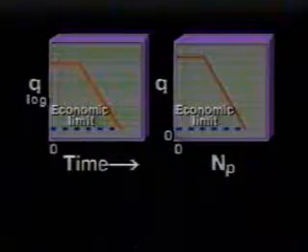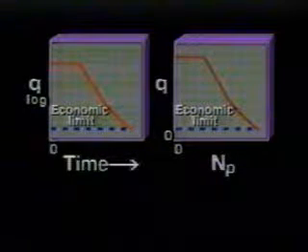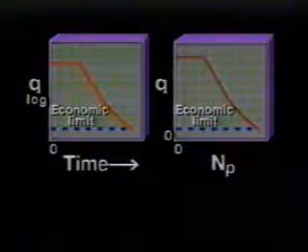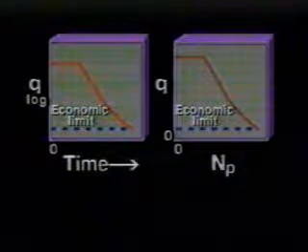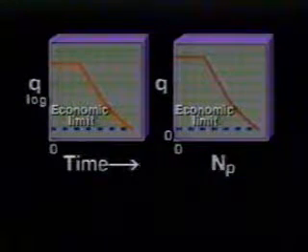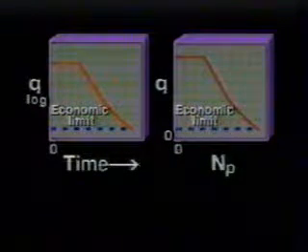We remember to spread out the production near the end of the life of the well, because the constant percentage decline curve tends to be conservative in this region. We now have our production rate versus time profile and our reserves.